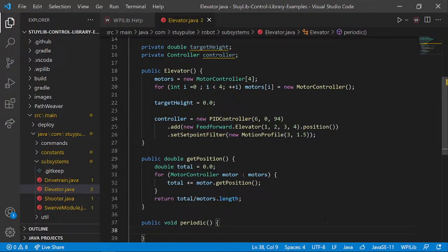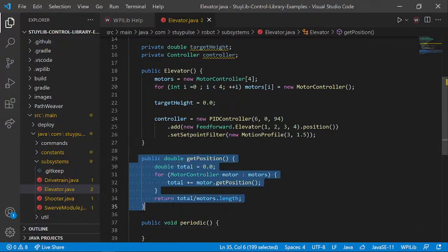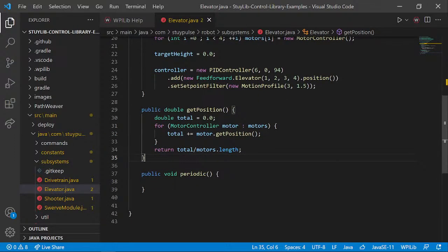If they're working together, you don't want 4 different controllers, because if they're all for the same gearbox and one is slightly below the target, one is slightly above, they'll be going in different directions, right? And that's really bad for the gears and such engineering. But this averaging out the position values is a pretty good solution, right? And then we just pass in this position. This also assumes every motor has an encoder, but if it's only one, you might as well just use the one, as long as you don't have 4 different things going on.